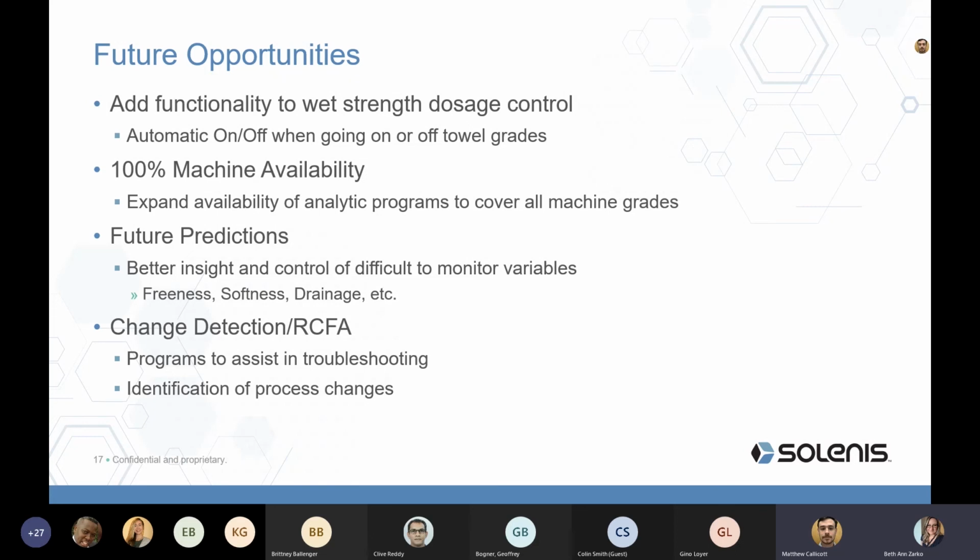It doesn't have to be tied to a prediction. It could be something else. It could be a lab value. It could be a sensor, information, as long as the data is there. And then tying that into correlated values or correlated tags that likely are causing the shift, that are running outside of where we expect, to quickly distill down a list of tags that can help him and his team go troubleshoot what's going on with the system.